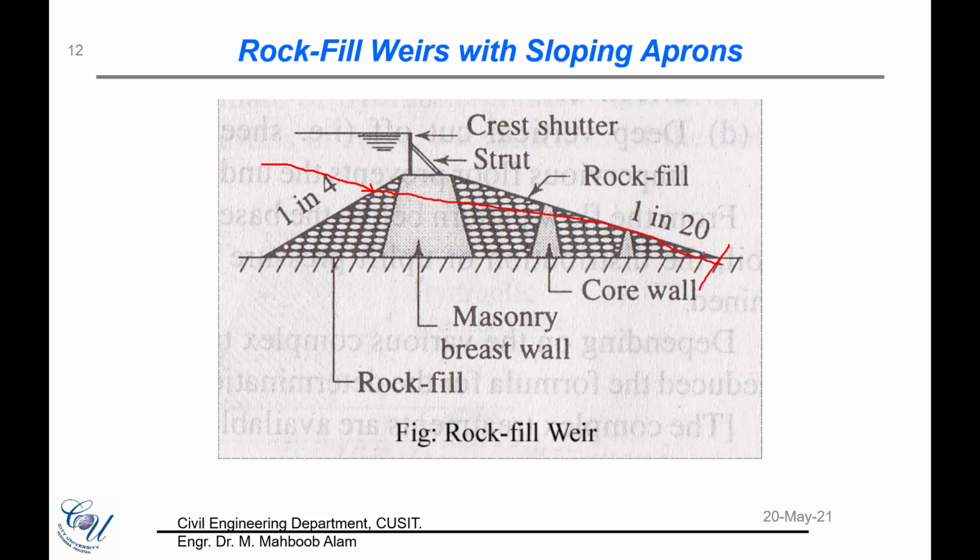So this has to be avoided. What we need to do is that once this water enters the dam or the weir body, it stops somewhere inside the structure. We collect this water maybe somewhere here, and then we safely transport this water to the downstream side or any other area.